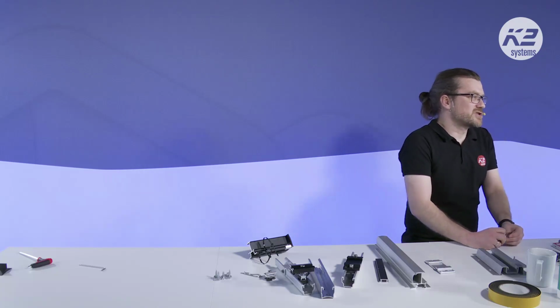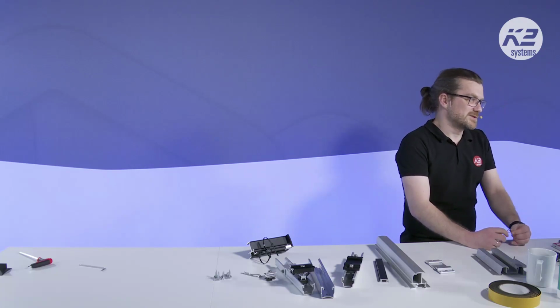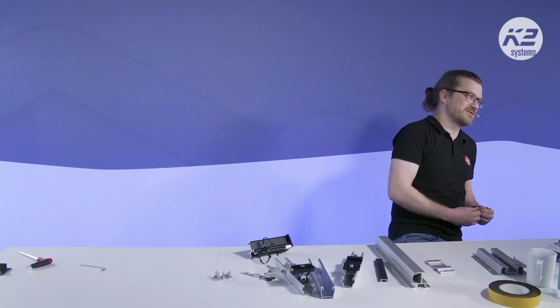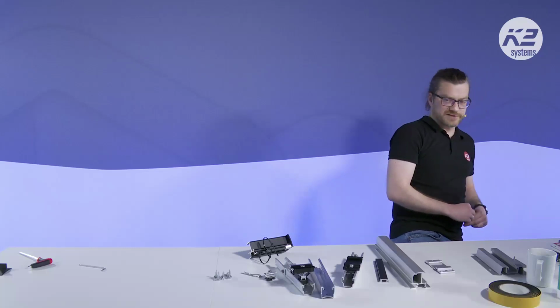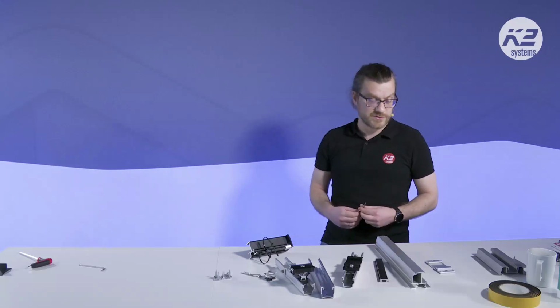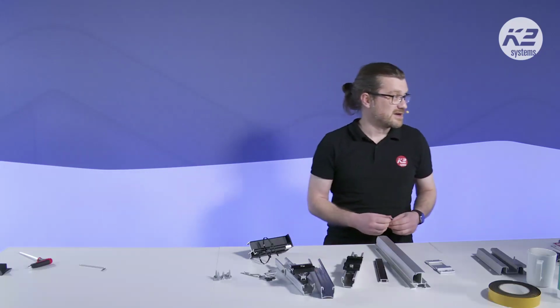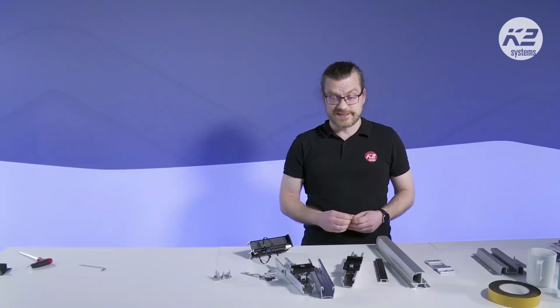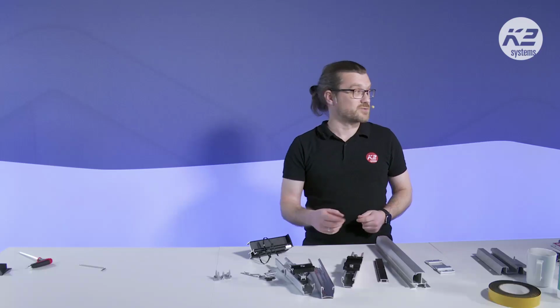This is the next question. Is it possible to install on a wave trapezoidal, corrugated trapezoidal sheet when the waves are not going from top to the bottom but from right to the left? I can say right away, if this is a trapezoidal sheet with crests, yes, you can use our mini rail instead of multi-rail in this way.